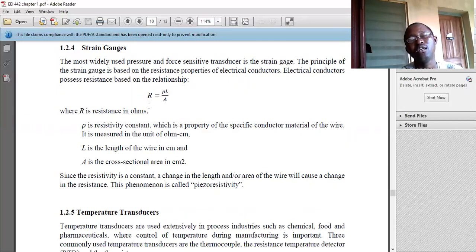So when you look at this formula, you see that the resistance you will get with a small wire will be larger than the one you will get with the bigger cable. This formula tells us that when you increase the length, the resistance will increase. When you increase resistivity, the resistance will also increase. If you change to a lower resistivity, then resistance reduces. If you increase A, resistance reduces. That is, when you increase the size of the cable, the cross-sectional area, the resistance drops.